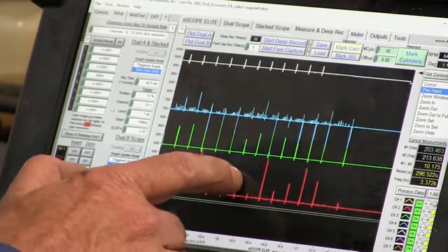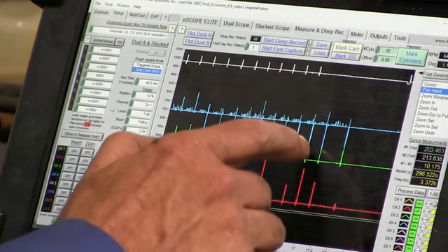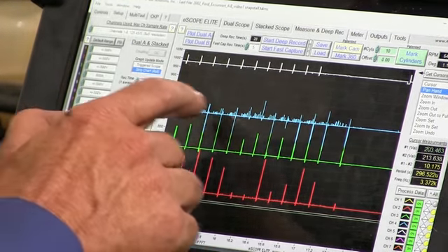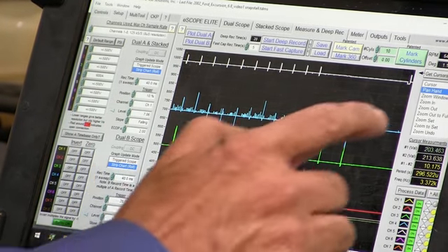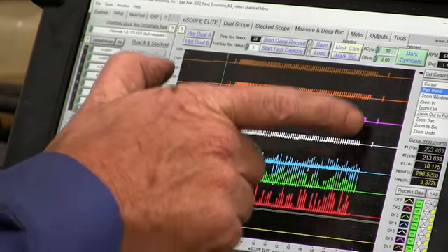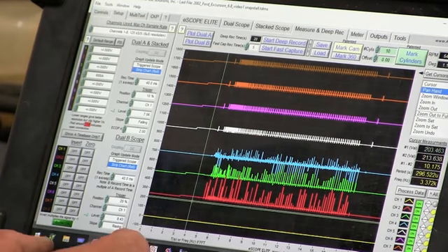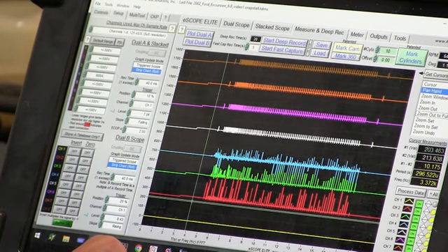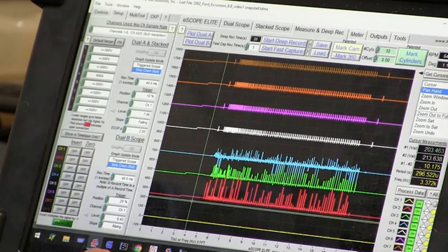I think it's internally arced. And it's going from the secondary to the primary and it's hitting it. And that's what usually causes it when I see this type of a signal with the amp clamp. I've done this quite a few times, guys. That's usually where my problem is. But you can see the torque limit command, and that's just because this signal is getting contaminated with the ignition. And those ignition pulses are edges that the computer counts, and all of a sudden it thinks that the shaft is going much, much faster than it really is.